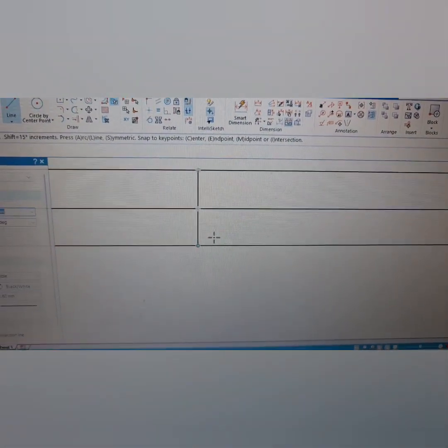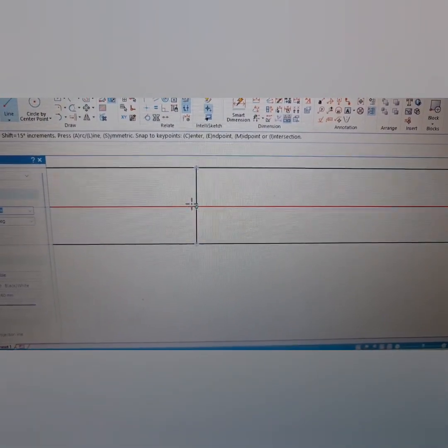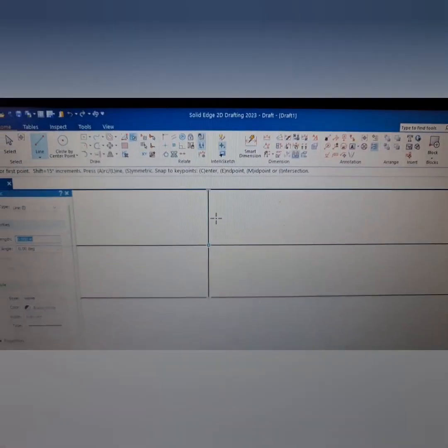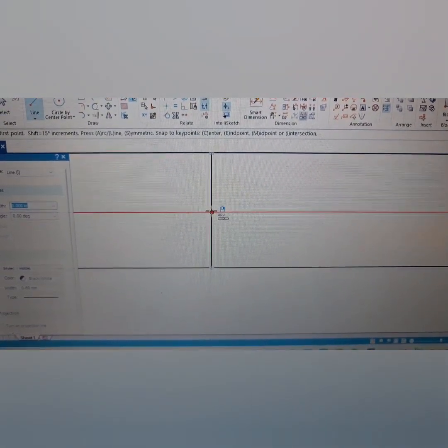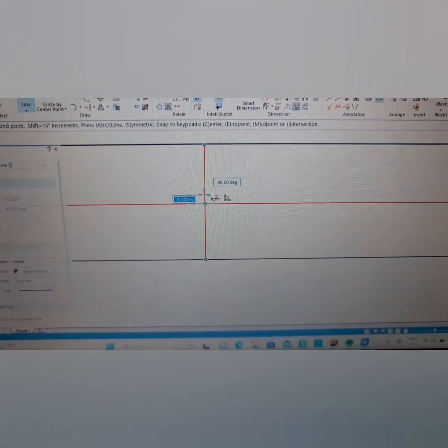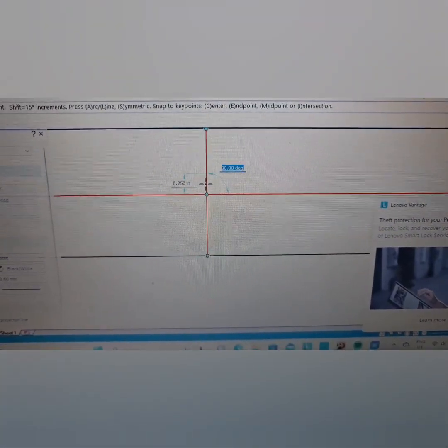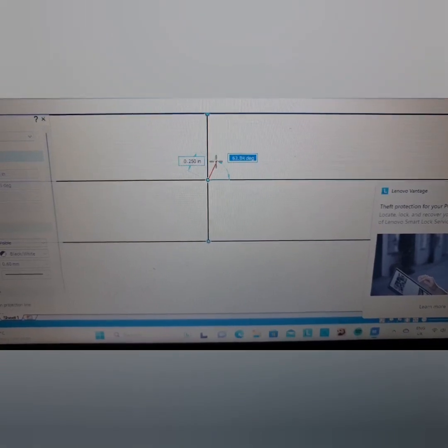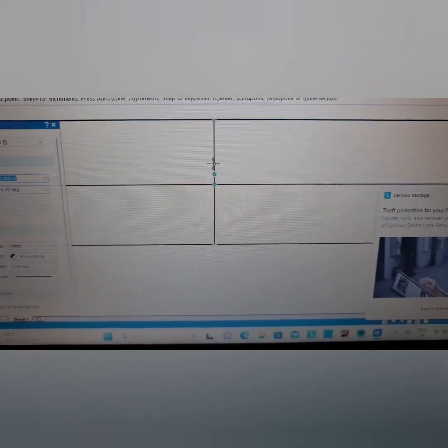Now I want to do a hook hole which is square, it is not square, some are square and some are rectangular. So what I do, and this might be a hard way for draftsmen to do it, but the way I do it, plonk my first line up, I want to go up 1/4 inch, 0.250, yeah, it's immediately put that line there, and now it's asking whether I want it 90 degrees or wherever, so I'm going to put it at 90 degrees to the center, yeah.